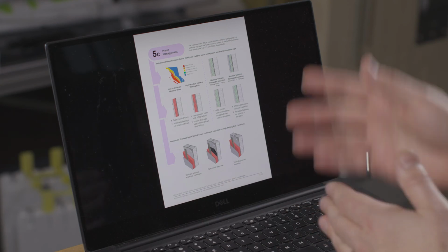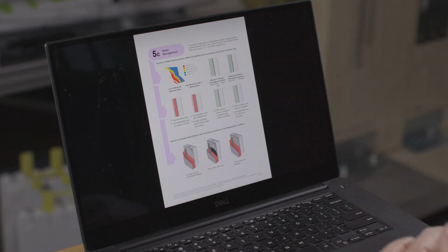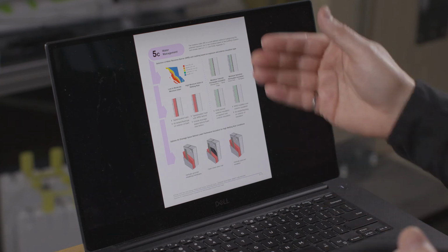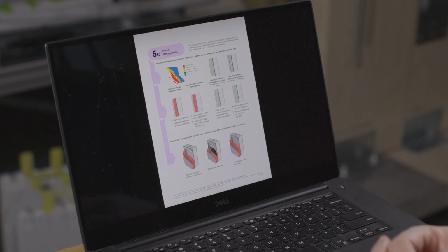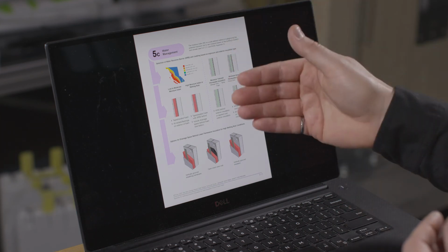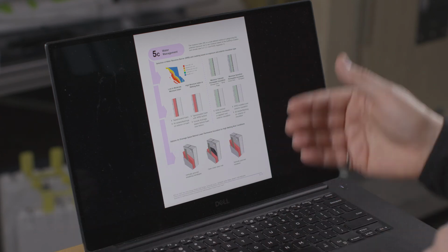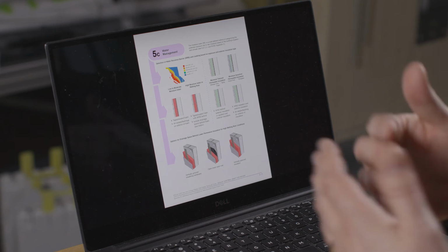Then on the right-hand side, we got vapor permeable insulation. And so you got moisture tolerant insulation versus moisture sensitive. The key rule of thumb there is if it's moisture tolerant, things like mineral wool, then the water resistant barrier can be inside of it. If it's not moisture tolerant and is sensitive, like things like wood fiber, then you need water control on the outside. Okay, and so that follows through into the flow chart there.